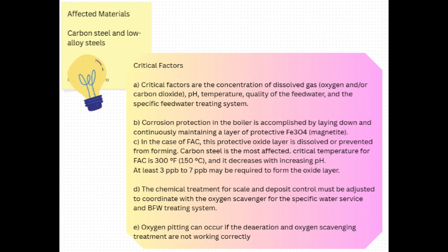It often does. And if you look at the damage, the way it looks tells you which gas did it. So the appearance is a clue. Definitely. The two main gases we mentioned, oxygen and carbon dioxide, they leave different fingerprints, let's say. Okay, start with oxygen. What does that look like? Oxygen causes pitting. So not general thinning, but small, deep holes. It's very localized, very aggressive. And the sources highlight it's particularly bad where water temperature jumps up quickly. Think closed heaters, economizers.